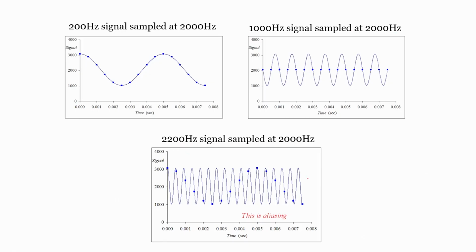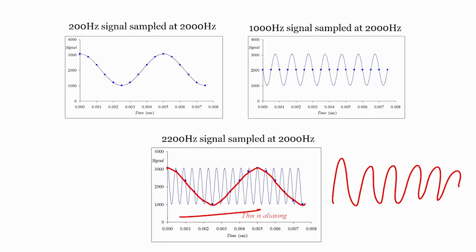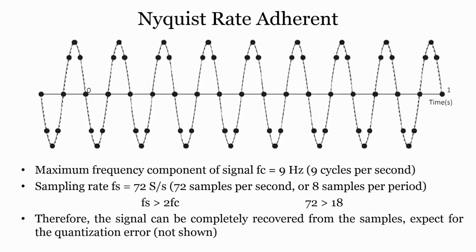Here you can see very clearly that there is an aliasing error, because if I reconstruct this signal, this is what I am getting, but what is my original signal? My original signal is this. It is not this, right. So, this is my aliasing error. That is why we should always have Fs greater than 2 times f max, right.